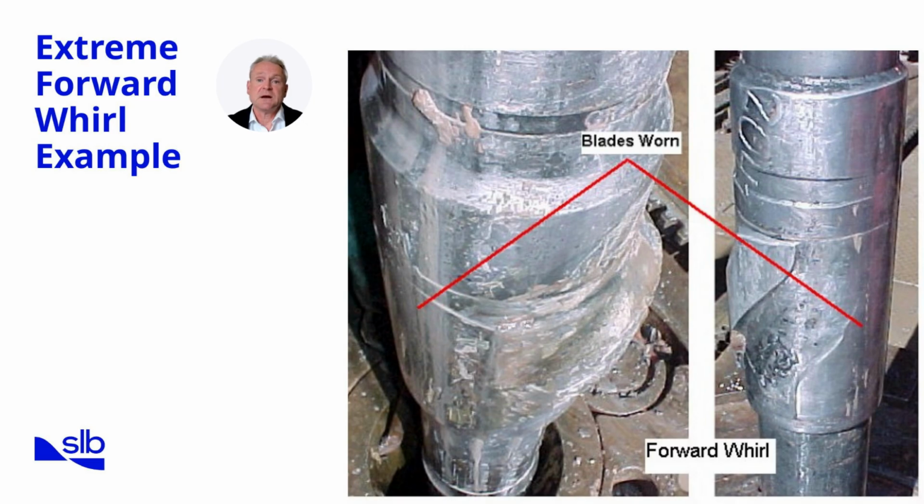Such damage not only weakens the tool structurally, but also reduces measurement reliability for any logging while drilling equipment housed in the same collars. The wear patterns are unmistakable. Smooth areas where the body has polished against the formation, alternating with gouges where impact forces were highest.